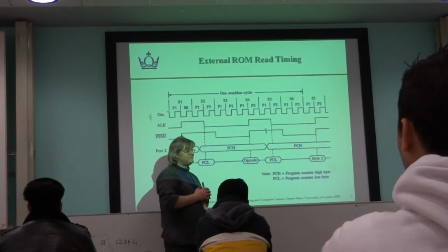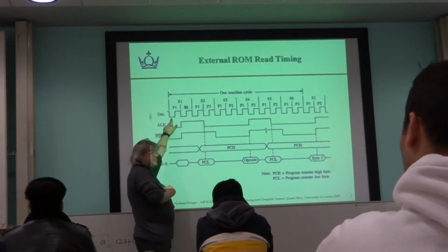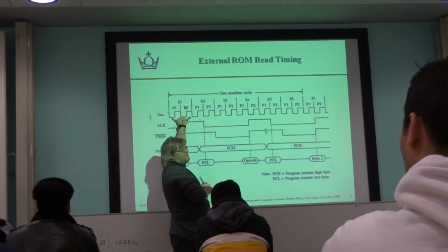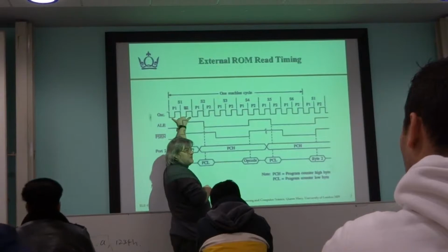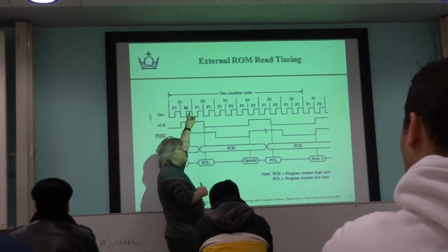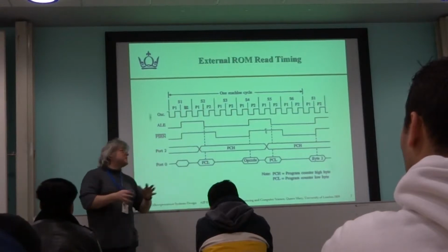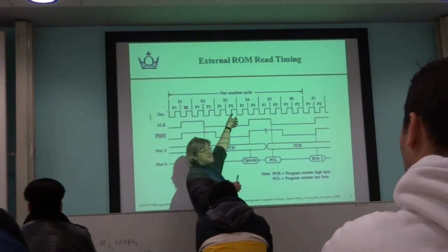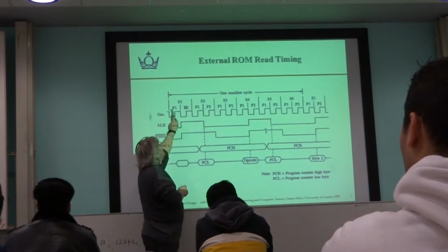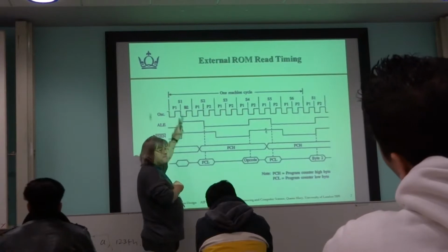Is a step a universal thing as 2 pulses? There may be other microprocessors that use fewer steps. And in fact, there are versions of the 8051 where effectively it can achieve everything in one step now. But in the classic 8051, it took 6 steps, 12 oscillator cycles. But no, there is nothing that's generic about that. That's this particular device. Now there may be others which do the same thing, but there could be others that might have 4 steps or 2 steps, and how many oscillator cycles per step. I don't know, I couldn't answer that. Fair enough.